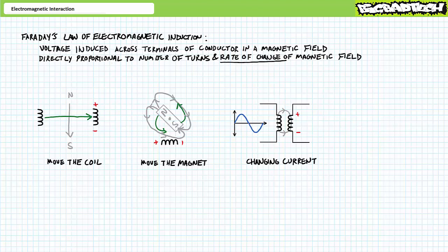Thus far, we've been considering the observed effects across an open coil with no load. What if the coil, with some induced voltage, was incorporated in a circuit, including a load? Follow this chain of logic carefully. Given a voltage is induced across the terminals of the coil, and the coil is part of a circuit, including a load, current should flow in the closed circuit. Given our earlier understanding of electromagnets, we could surmise that this new flowing current will create its own magnetic field.